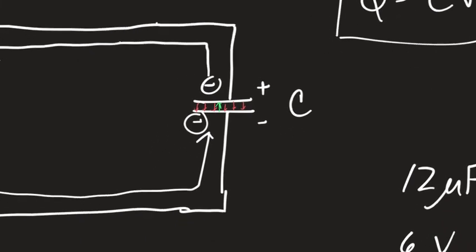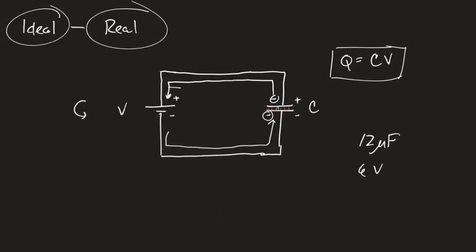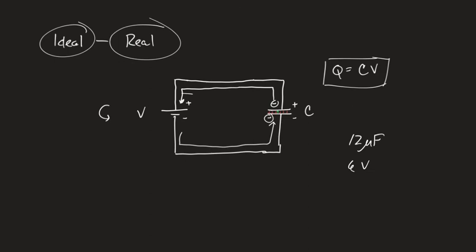So if you've ever turned something on, heard some kind of crackly noise, and saw blue smoke escaping, you now know what probably happened. You probably fried a capacitor. They are the number one component to go, especially as a power supply begins to malfunction in a computer or in your game machine and stuff like that. It is the capacitors that tend to be the things to go first. And trust me, do not inhale the blue smoke. You will be unhappy with the results.